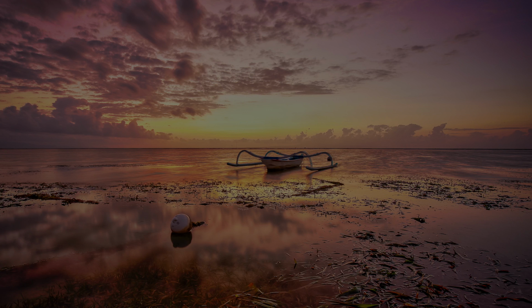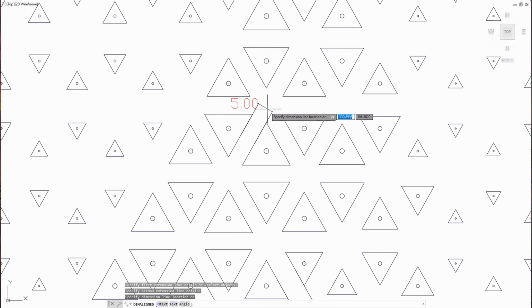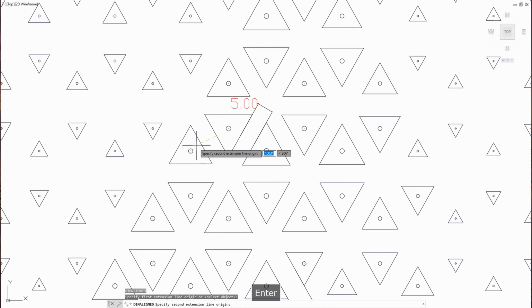From here, we have two DXF files. The first one is when we use the ideal shape and let the inscribed diameter be calculated automatically. And another one is when we use the non-ideal tool shape and we specify the inscribed diameter manually. Let's open the Laser Mode Ideal and check the minimum gap. From here we can see that the minimum gap is satisfied. Then open the Laser Mode Non-Ideal.